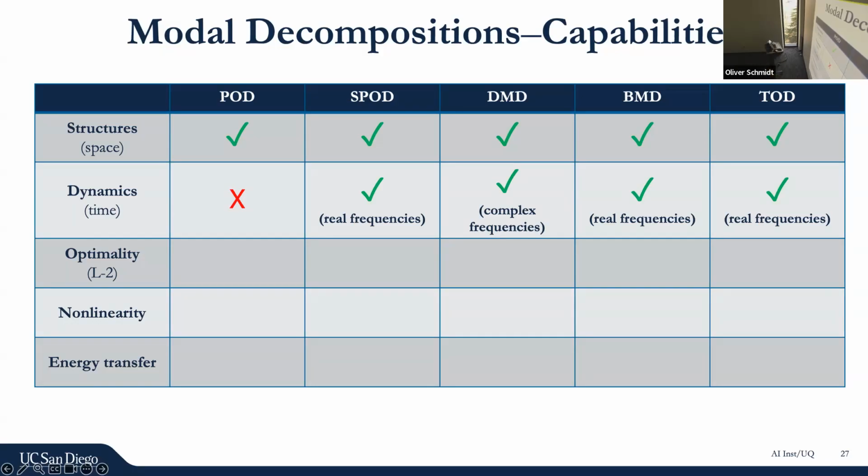That's also one of the reasons why I hopped on the SPOD algorithm. They're computed in a very similar way. There are different ways of computing it, but the vanilla version that I showed you earlier, the spectral estimation by segmentation, we used for the first versions of these methods too. Optimality, they all have it, but not DMD, since it's based on an evolution operator. It's a little bit different.